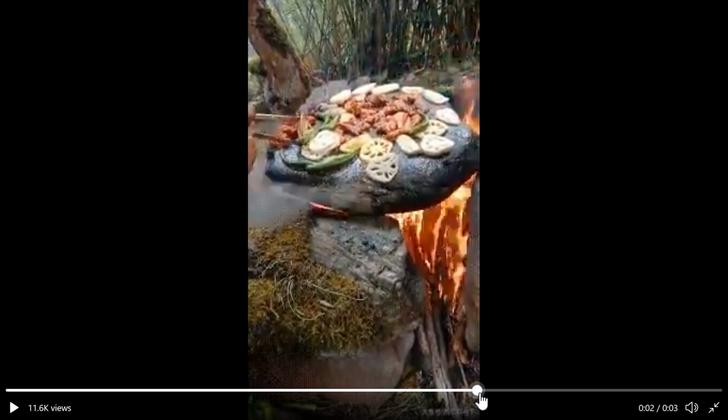So what's going on here? It's exactly what we mentioned before. At some point, this rock might have been saturated. Probably they picked it up from a river nearby, and if it is fully saturated when heated up, and if the rock has permeability which is low enough so it doesn't let the pore pressure dissipate, eventually it's going to fracture.